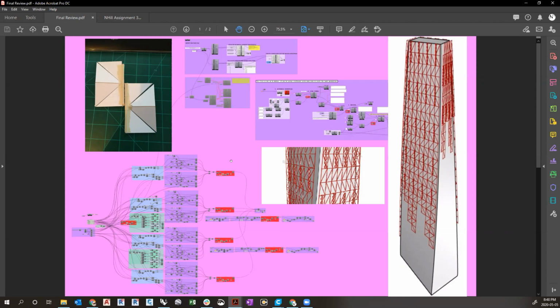But also in a lot of ways, purely talking about fabrication, something like a CNC machine can only do overcuts and not undercuts like 3D printing can offer. So then you're actually starting to pick one fabrication process over the other as well. It then doesn't just become a form finding exercise, but also why you would pick a particular kind of fabrication process, which links back to the design in one way or another.